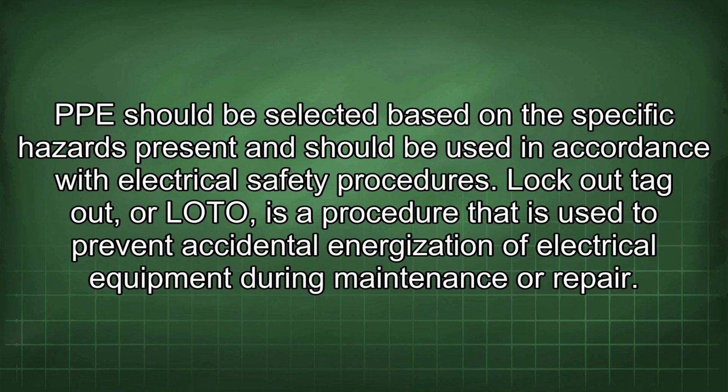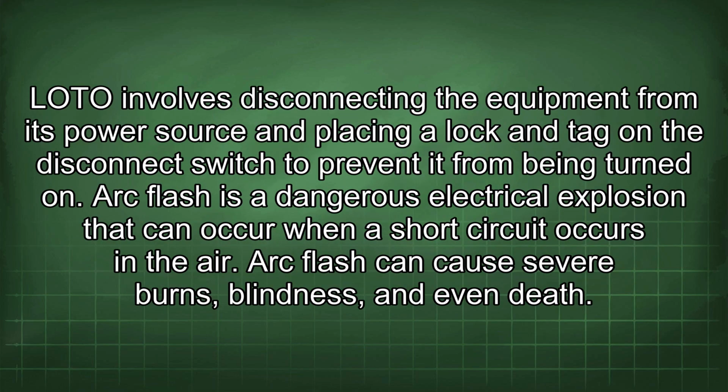Lockout-tagout, or LOTO, is a procedure that is used to prevent accidental energization of electrical equipment during maintenance or repair. LOTO involves disconnecting the equipment from its power source and placing a lock and tag on the disconnect switch to prevent it from being turned on.